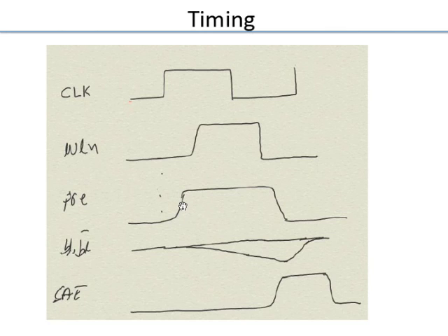Remember the pre-charge transistors are PMOS transistors because you want to pre-charge the node to VDD. So to shut off the PMOS, the pre-charge voltage goes from 0 to 1. Then the bit lines start discharging, and after some time the sense-amp enable kicks in to turn on the sensing. So these are the basic signals which we need to generate for your SRAM to work.